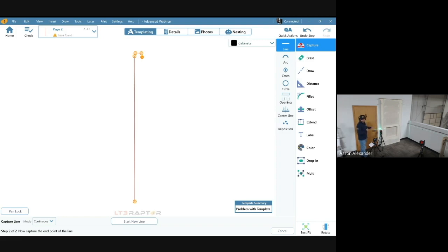If we do a scribe across the face, again, I'm aiming onto the face of this now to create the front edge of that miter return. It's the boundary object that we want our stone to stop at. And then we're going to add material thickness and glue to that. So here we go. Shoot some points down the front here. And as I switch to the cabinet color, because we're going to edit this edge into a miter cut, I'll get some windows between my tripod I got set up there.